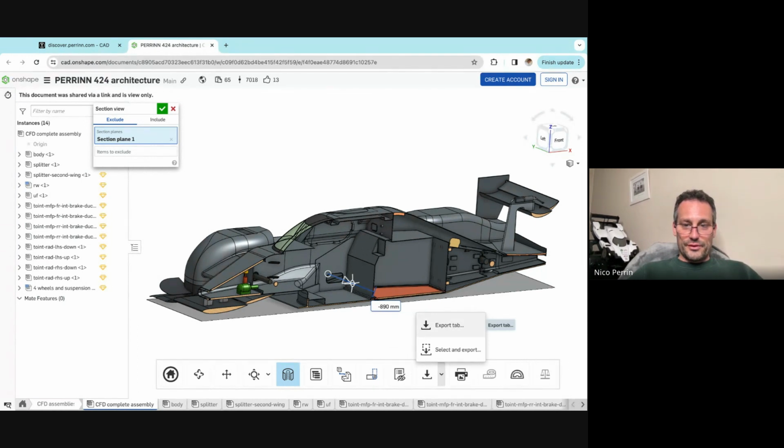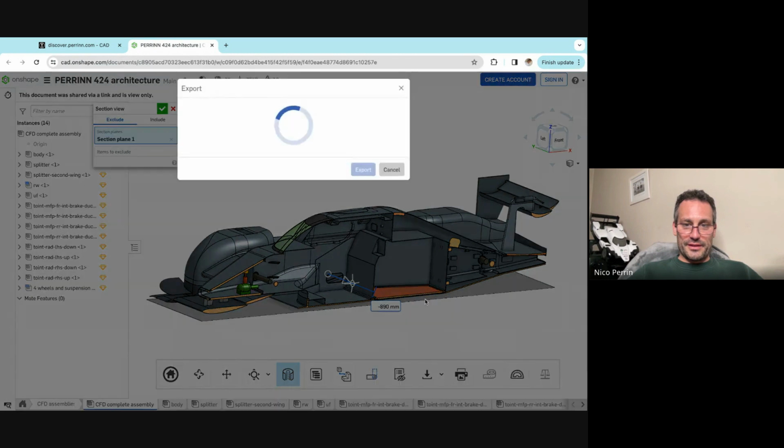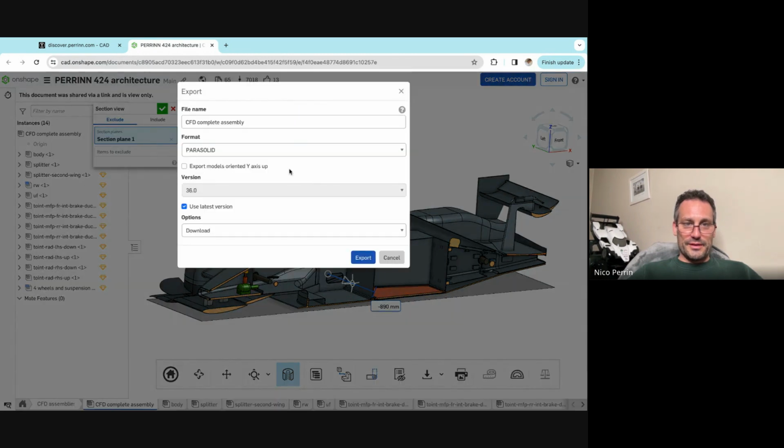If I go on either select certain parts and export them, or you could export the geometry here. It will ask you in which format you want to export. And as you can see, you can export in all of the main formats that can be read by other software. I typically use Step if I want to have a good quality CAD that is used somewhere else.